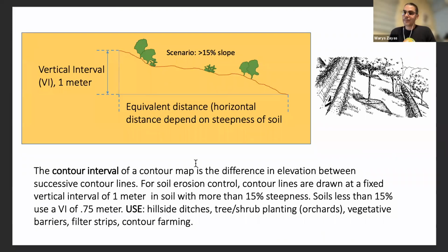There are surveyors with really technological equipment, but you don't need all of that equipment. You can just measure it using a clear hose with water inside, what we call a water level, and a measuring tape or any other scale that is useful for it.